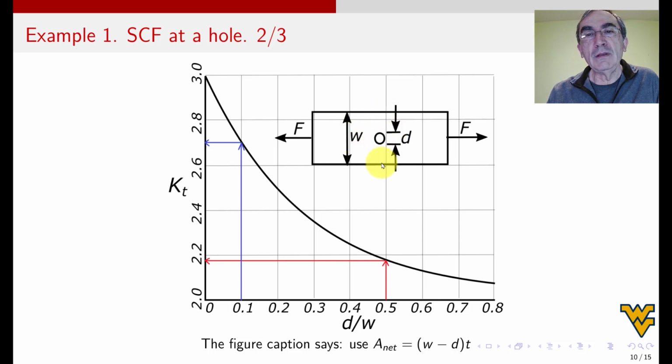So if it's in an infinite plate, the value is 3. For holes, the maximum value of KT is 3. There is an analytical solution and proof for that. And it's nice to remember, because if you don't have the chart and you're in a rush, well, the KT for a hole cannot be more than 3. So you can use 3 and it's conservative. Later, when you get your hands in the chart, then you can correct, and then you realize for this geometry it's 2.7.